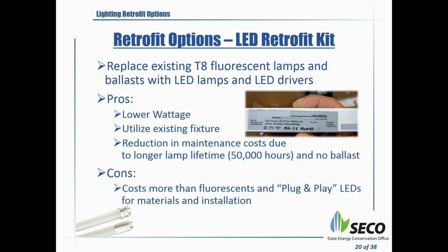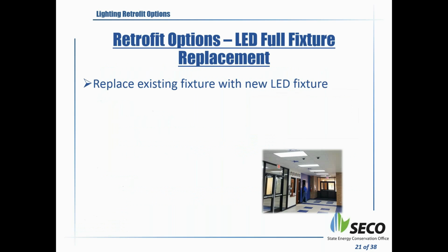The cost is more than fluorescent plug and play. We call them plug and play when you take the old lamp out and put a new one in. The reason it costs more is that you have to rewire it. You have to take the ballast out. You have to have an electrician doing a lot of this stuff. So the first cost and installation cost is more. That's something to keep in mind.